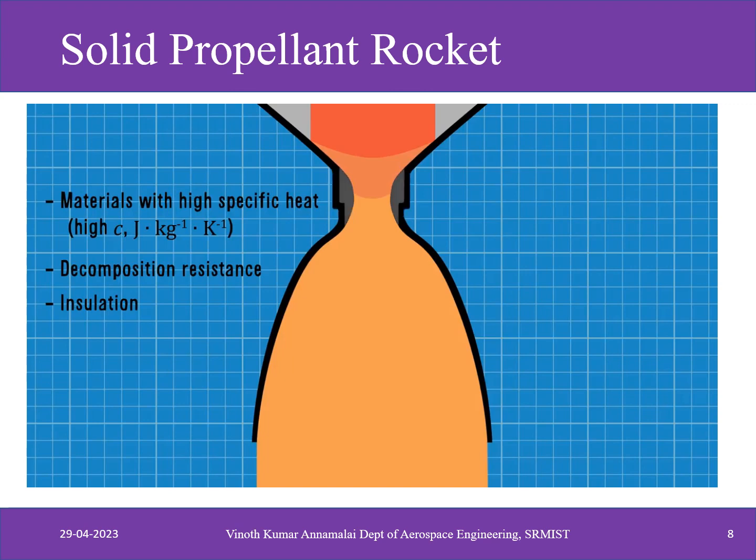A throat insert can be used in extreme circumstances. A throat insert is usually made of a high-grade graphite. It has great properties at the extremely high temperatures it will be heated up to. The gas at the throat might not be the hottest, as you've seen in the second episode, but it is the point where heating is the largest, due to the small circumference. Here we have a graph showing the heating per unit surface area throughout the nozzle.